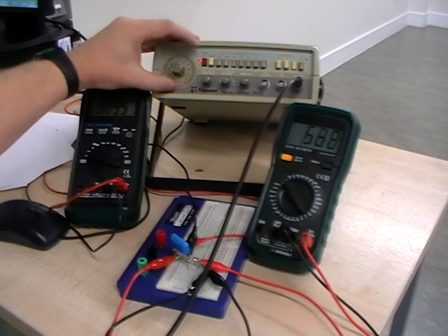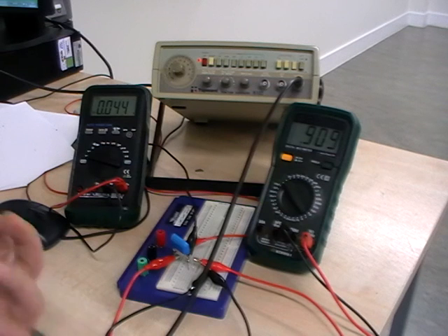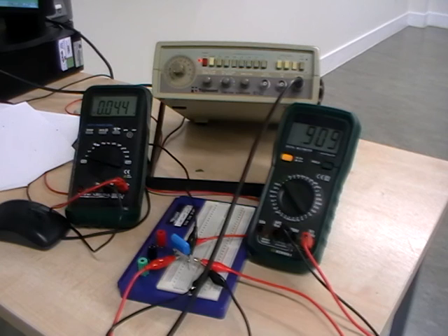Go to 10 kilohertz and see what it does now. The signal generator doesn't spit out as much juice. The signal has gone right down. But again, we are just looking at ratios, so it doesn't really matter. We have just about a volt across our resistor. But when I look at our capacitor, it's only dropping about 40 millivolts. So we've got almost a volt, and then 40 millivolts. So the ratio has gone the other way around now.